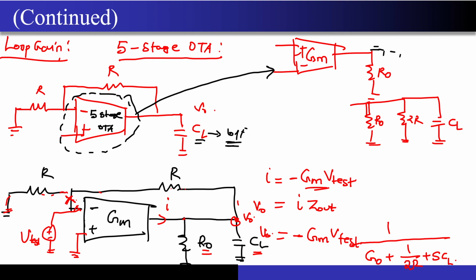Now remember, what is the voltage that is coming back at the input? I have V0 over here, correct? And at this particular node, I have the output voltage, then I have R, then I have R, correct? This is grounded, and this is where my loop was coming back. This is where I had broken the loop, remember? This is where I am applying the V test voltage. So what is the Vx value that I am getting over here? This is nothing but the resistive division of this V0, which is just V0 by 2, correct? So let me just write this as equation number 1.